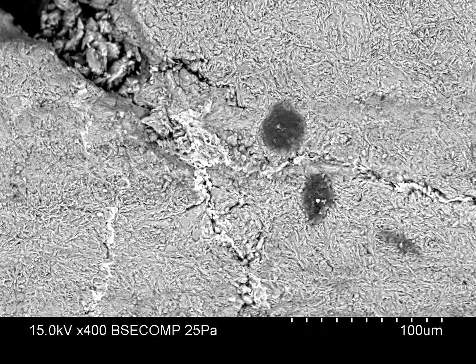A bit further down on the seal boss section, we have the BSC image of the crack that I mentioned before. And you can see the white material, which is a remnant of the surface veneer that has leaked into this crack during manufacture.